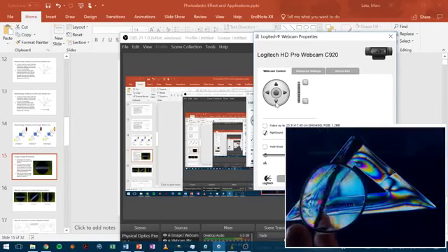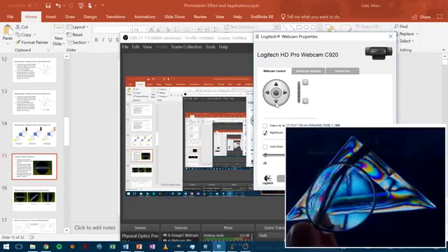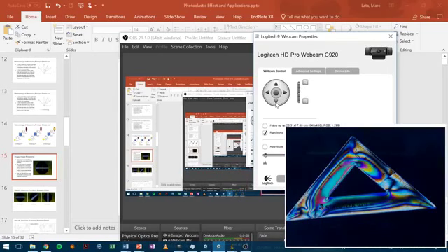So the stress distribution is nearly nothing. Oh, nice. It is well heat treated after production. Do you know what is meant by heat treatment? After production of any mechanical part, there are a lot of internal stresses embedded during machining. There is some heat treatment to release all internal stresses.